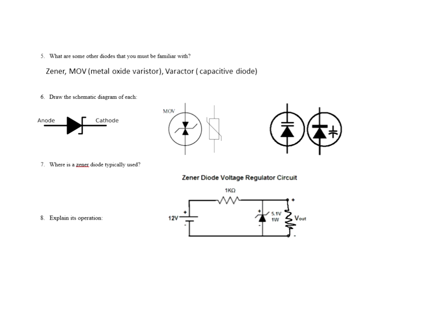A little more information here that you don't need to know for the exam. This and this form a series circuit, so whatever voltage I have here, the remainder is there. So these 2 voltages have to add up to the 12-volt source. But anyhow, the most important concept here, explain its operation: a Zener will conduct in reverse bias to limit its voltage on its terminals to the Zener voltage.